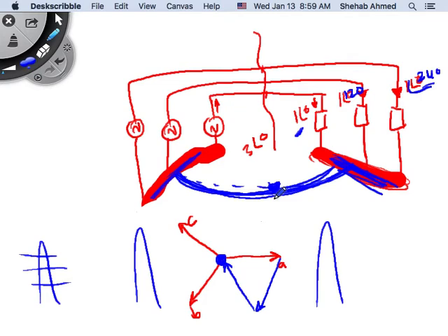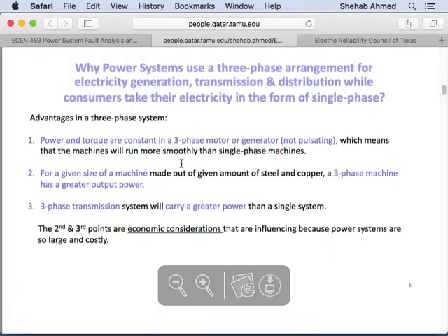So they can supply a different area using two different methods. And if one method is going to cause more unbalance than the other, maybe you supply it with another method, right? So in Qatar, we actually have a distribution control center and a transmission control center. These guys are sitting there looking at things happening in real time all the time. And I will show you a video of something like that.